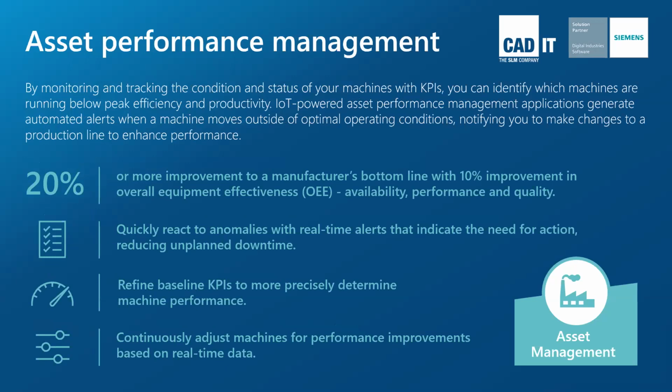The next use case I wanted to talk about was actual asset performance management. So this is about monitoring and tracking the condition of the asset and the KPIs within your asset, but using OEE to showcase how well that asset's performing. So rather than just monitoring the actual conditions of the process against set limits, there's the standard OEE, overall equipment effectiveness, metric. It sums up the availability, the performance, and the quality of the product coming off our asset to give you an OEE KPI score.